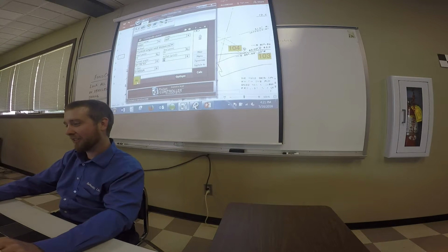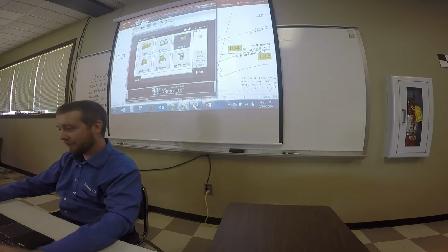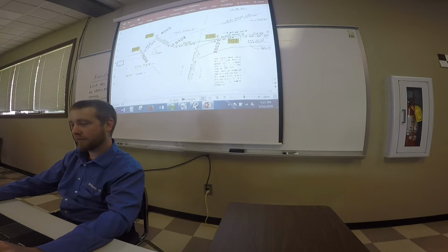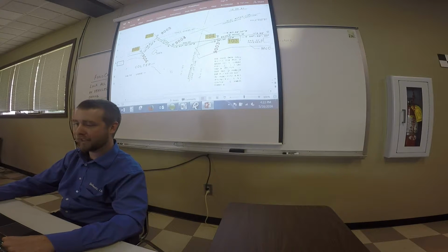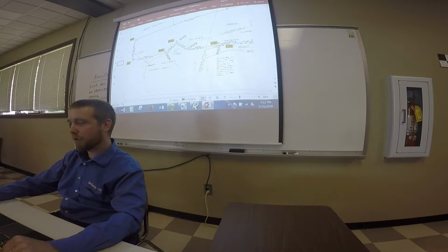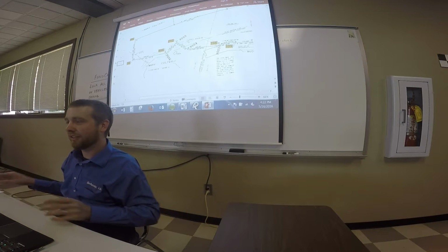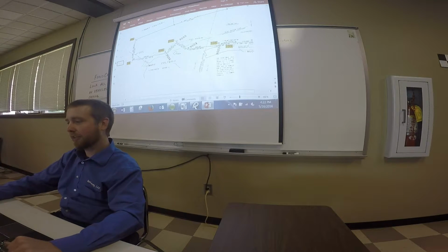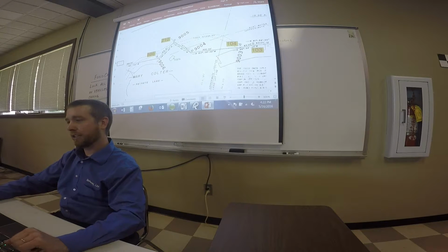All right, so now that's what you do if you don't have any data at all. Now, what do you do if you want a turned angle, but you have stakeouts already? The PM ahead of time keyed in this plat and made you a whole bunch of 9,000 numbers. They're just sitting off at 8,000. They don't match the survey at all. They don't match your points at all, so it's completely off by itself. Well, you can translate and rotate those, or if it's just one point that you need, you can just do a turned angle to get the same thing.